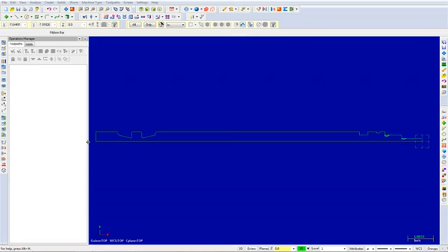The first thing we need to do is select a machine definition. To select this definition, choose Machine Type, Lathe, Default. You should be able to see the default machine definition in the Operations Manager. If you cannot see the Operations Manager, press Alt-O on your keyboard to see it.